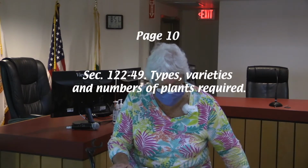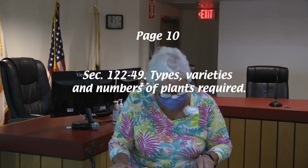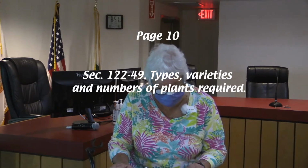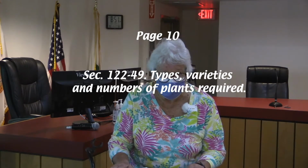Types and varieties and numbers of plants required. We're going to go right through 1, 2, 3, 4. Number 1, and remember this is something you're going to need to know: each required vegetation buffer shall include at least one large or medium tree for each 75 square feet of the required buffer area, with a minimum of 6 different species of native plants included.